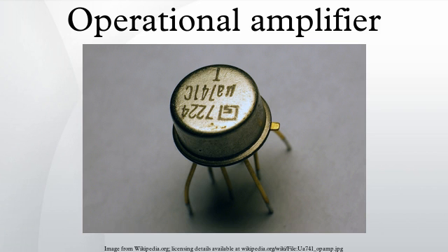The magnitude of AOL is not well controlled by the manufacturing process, and so it is impractical to use an operational amplifier as a standalone differential amplifier. Without negative feedback, and perhaps with positive feedback for regeneration, an op-amp acts as a comparator.